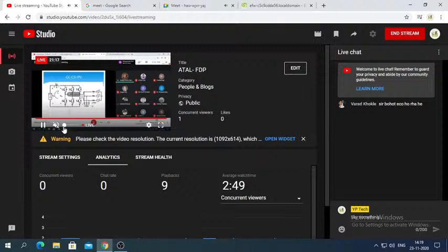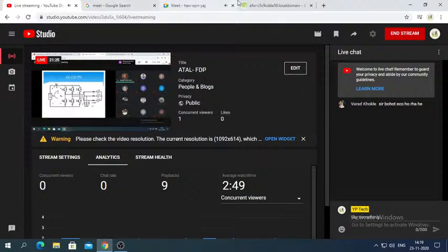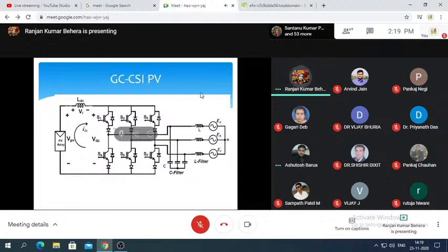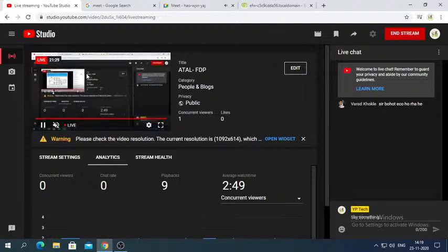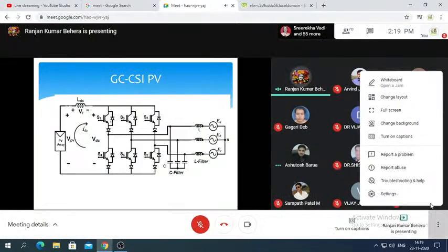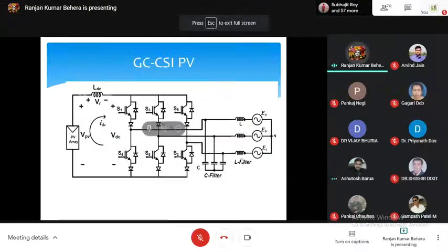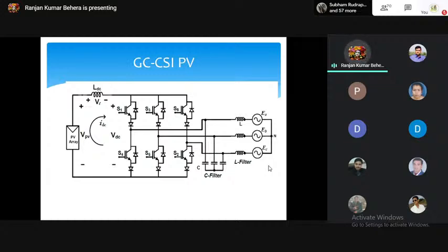You can control the current, but you cannot control the voltage. So for controlling current, we have a unidirectional switch. You can see after this IGBT, there is a diode connected in series, which makes the complete device a unidirectional device. That means the current will flow in one direction. The voltage can be reversed, but the current cannot be reversed in a current source inverter.